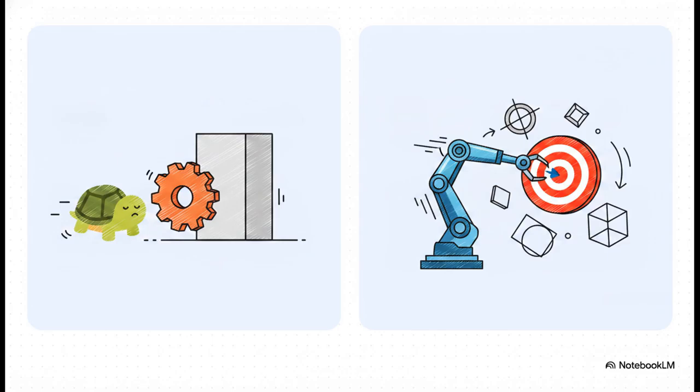With scalar control, it's super simple to implement because it just keeps voltage and frequency proportional, but the trade-off? A pretty sluggish dynamic response. You definitely can't use it for that high-speed robot arm we talked about earlier. On the other hand, vector control, or FOC, requires a highly complex mathematical implementation. However, by decoupling the magnetic flux and the torque, it delivers extremely precise, high-end dynamic performance.